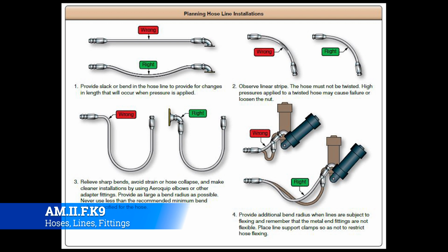And so effectively that twist, I mean, you just think about taking a drinking straw and twisting it on either end, and it's going to narrow the inside of the straw because you're starting to roll it over on top of itself. Well, imagine that you pressurize that. Now, if it's rated for 10,000 psi, you've basically taken the rating down to 5,000 psi, but you've maintained the hydraulic pressure at that 10,000 psi, and there's nowhere for it to expand. And so now it's under what it should be able to hold by design, and there's nowhere for it to absorb that extra pressure, and so it's a surefire way to cause a break.